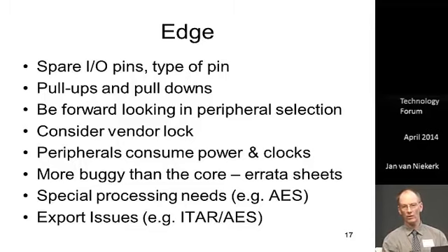There's a very important one which I call vendor lock. I just saw a classical example of that just a few days ago, where one vendor said, I'm doing this ARM processor, but I'm putting in this very special peripheral. And of course, if you fall for that, right at that point, that vendor has you locked. So you have 20 or 30 vendors that you can choose from for your microcontroller. But if you choose a very special peripheral from a very special vendor, then you're locked to that vendor and he can decide what he wants to charge you, because you can't go anywhere.